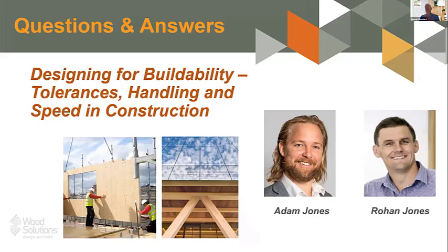Just back on moisture, a question from Adrian: would you ever consider painting and sealing the panel sides to prevent moisture ingress? Would that ever be a problem or a thing you'd do? Yeah, we would put resin Lignagard on the end grain, so we would deliver it with that on. If it's going to be out in the weather for an extended period of time, I think it gets you 3 months protection. But it'll just hold it there. If it just ponds up and you don't do anything about it, it will still find a way in. But you can look at putting it on the face as well as the end grain to get that extra bit of protection on site.